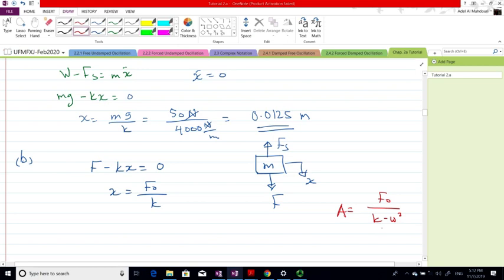If omega is approaching infinity, then the amplitude is going to be 0, right? But if omega is approaching omega naught, which is the natural frequency, then the amplitude is the maximum, right? You remember the resonance? If the applied force frequency is equal to the natural frequency of the system, then we have the maximum, which is the peak of the displacement. So the theory is correct.